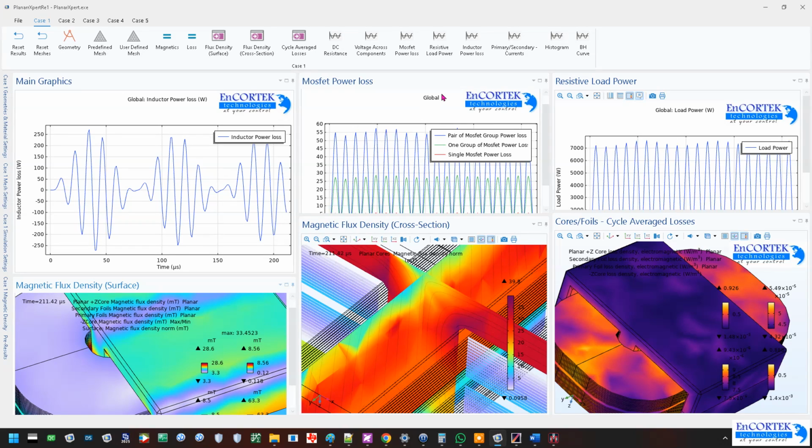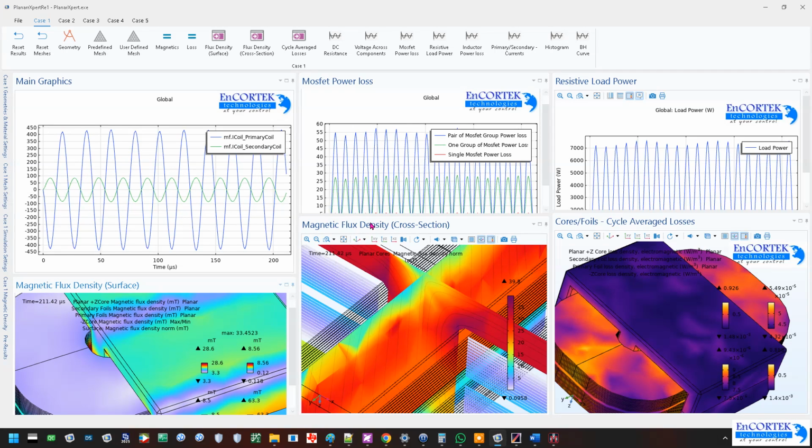So that's that. I didn't bother to show the capacitor because the capacitor power and current rating is pretty much in parallel with the inductor, according to the topology that I use. So both of them will have about the same in that sense. Once you see this, I know the capacitor current going through. I will put a note for that. Now the inductor, primary, and secondary current. We can see a high current in the primary side and a low current in the secondary side. Well, the ratio will be different.